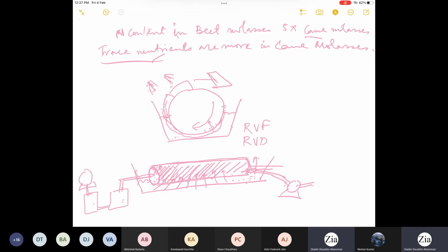The depth of this blade can be varied, so you will make sure that it will not touch the filter cloth, but you will maintain a minute gap between the filter surface and the blade surface. Whatever residual cake is there will automatically get removed by this blade. Just after the blade, you will have a collecting tray, so whatever you are removing will not go back to the liquid. It will get collected on a tray, and then you will take the cake and process it subsequently.